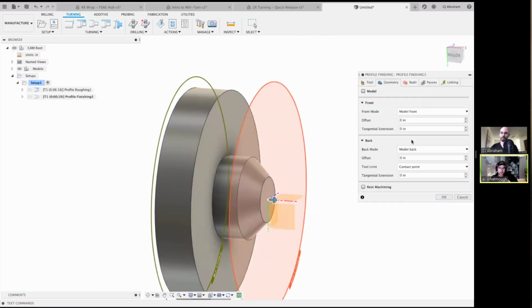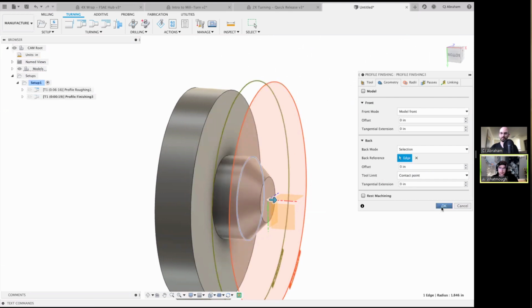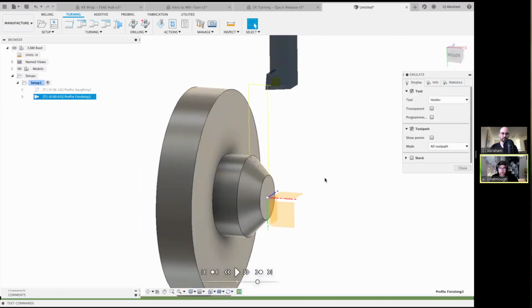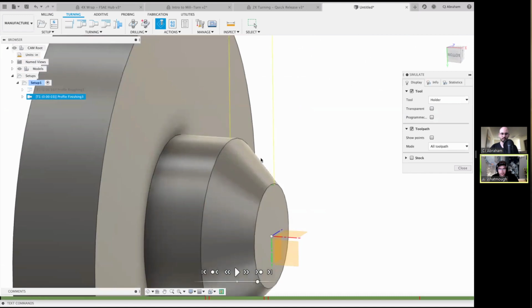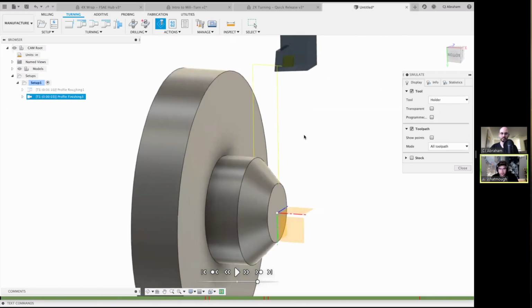And while you're doing that, this is just another point for generally across Fusion as a CAM system, but most specifically with turning in 3D. The best thing you can do is make as few selections as possible, have the system calculate a toolpath for you, and then start to refine the toolpath. Just like what CJ did, throw the toolpath on it, machine the whole part, and then start to constrain it. It's a little less applicable in 2D where you have to pick geometry or it's really geometry driven, but still even there, I'd strongly recommend folks get a toolpath first and then modify from there instead of setting 1,000 options right at the beginning.